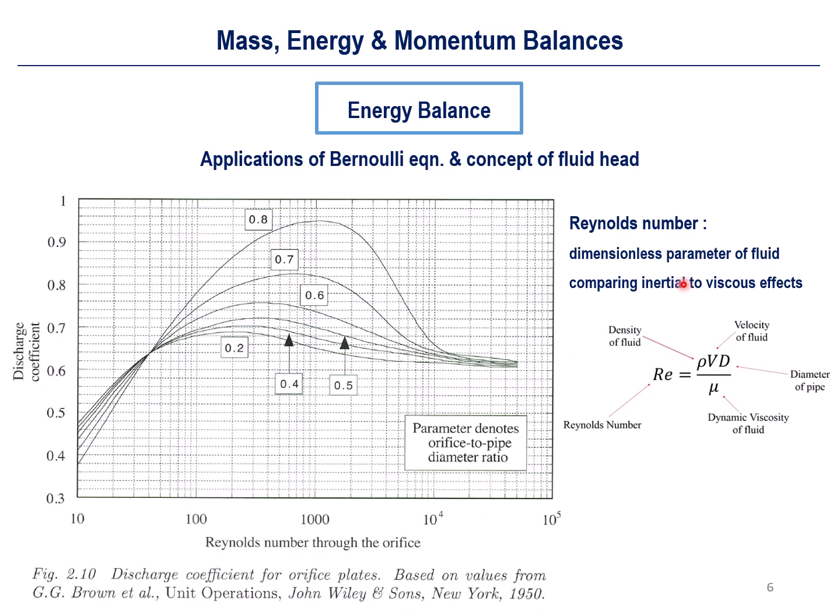This dimensionless parameter measures the relative intensity of the kinetic energy relative to the viscous energy. So if you have a higher Reynolds number, it means that your fluid is moving very fast, or your fluid has very weak viscous friction. So the Reynolds number is equal to density times velocity times some physical size, divided by viscosity.